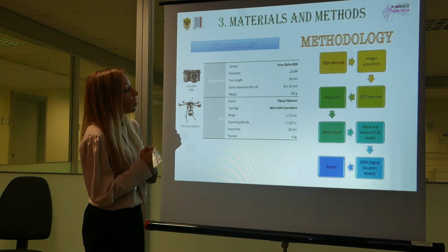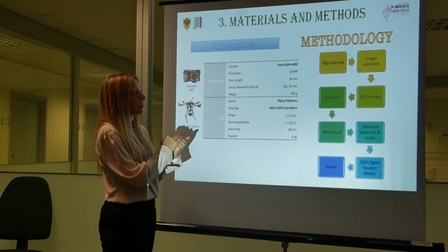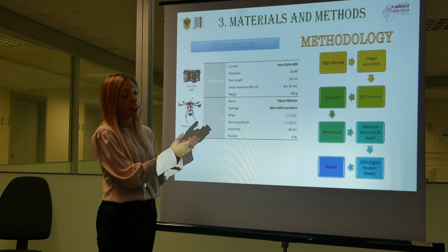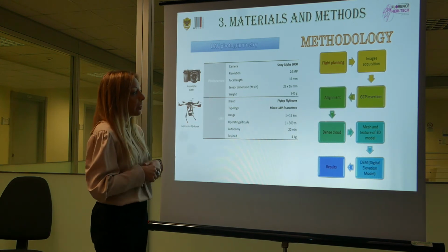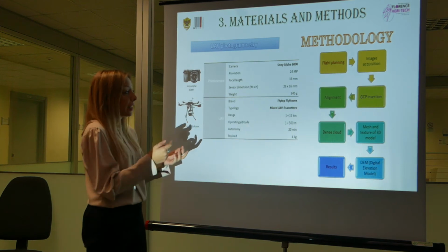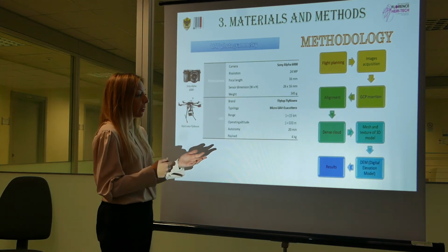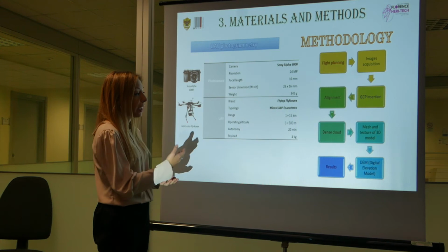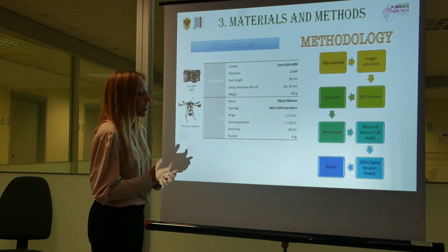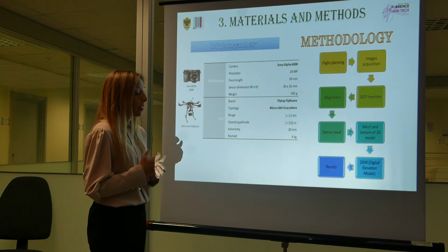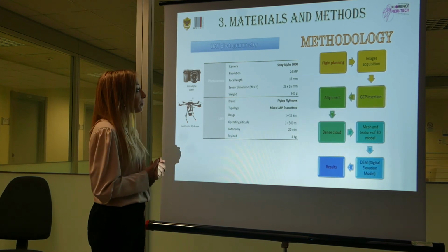For the methodology, we started from flight planning, and then image acquisition, and then we inserted the GCPs, then the alignment. Then we obtained the dense cloud, the mesh and the texture of the 3D model, and in the end we obtained the digital elevation model, the DEM, and the results, the orthophotos.